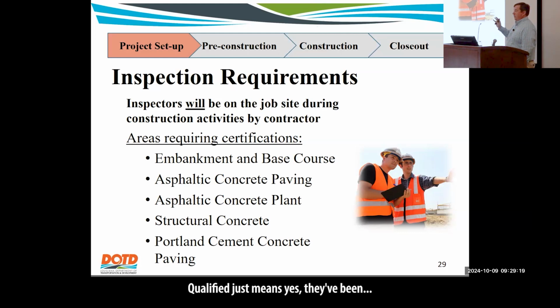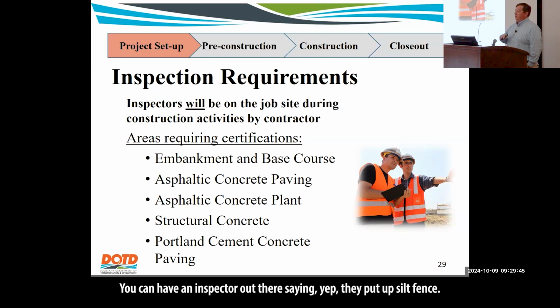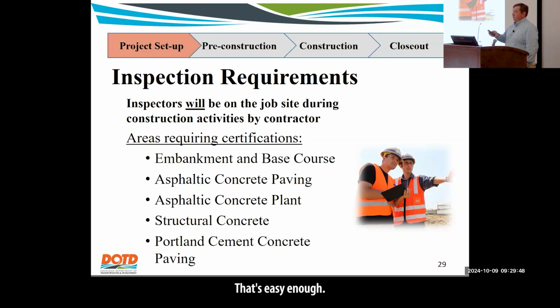Qualified just means, yes, they know what to do on a job, but like pipe, pipe doesn't have a specific certification. They can watch and put in the pipe. Now the backfill has to have density run, so you need somebody certified to do that. But there's no certification for striping. There's no certification for erosion control, things like that. You can have an inspector out there saying, yep, they put up silt fence, that's easy enough. They put up hay bales, those sort of things. But a certified inspector has to be out there for these sort of specific things.